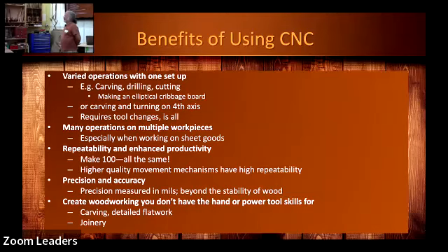Excellent point. That brings up a great point, which is the repeatability in design work. As an example of that, one of the things that Vince has used and we'll talk about is a program called Cabinet Sense, where you get to lay out cabinets. And what we've learned is that once you lay out one cabinet using parametric design, which means it's easily scalable, you can create cabinets with that same basic shape and scale them in any dimension and get repeatability that way.